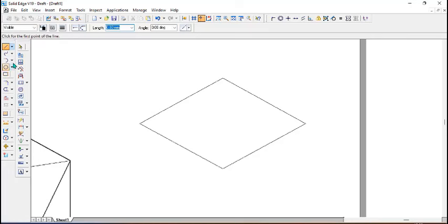The first and foremost thing here, there are 2-3 ways in order to draw the circular base in ISO. So we'll go with a simple one like a tangent arc. In the arc you will get a tangent arc. So you can select the midpoint of a line and midpoint of an adjacent one, and again midpoint, again adjacent midpoint, and again endpoint, midpoint, and last again midpoint to the end. Okay, so this is the one way by which you can draw the circular base.